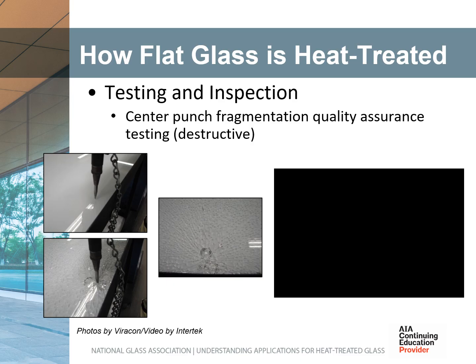The center punch fragmentation test method was developed by the Glass Association of North America, now combined with NGA, in 2004. It is known as GANA 101-04, Standard test method for center punch fragmentation of fully tempered flat glass. This test method covers the destructive fragmentation and evaluation of the fracture pattern of monolithic fully tempered flat glass products intended for use in architectural safety glazing applications.